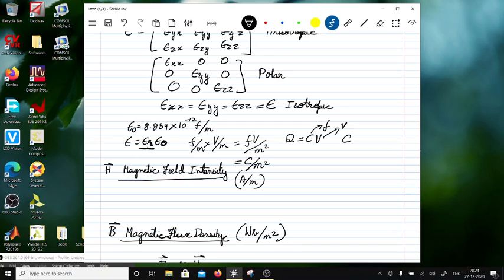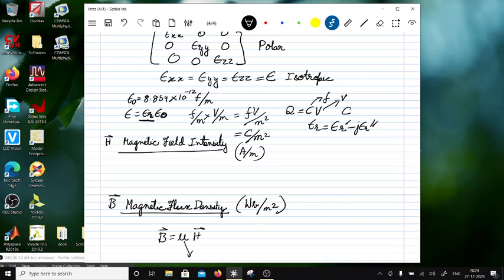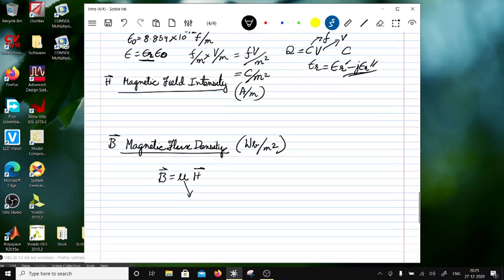So this basically is the free space permittivity, and the overall permittivity is a number multiplied by that. Now this epsilon r is very interesting because it can also be complex: epsilon r dash minus j epsilon r double dash. Okay, so when we talk about dielectric losses, we are talking about the imaginary part of epsilon that will be leading to dielectric losses. So we will consider this later on.